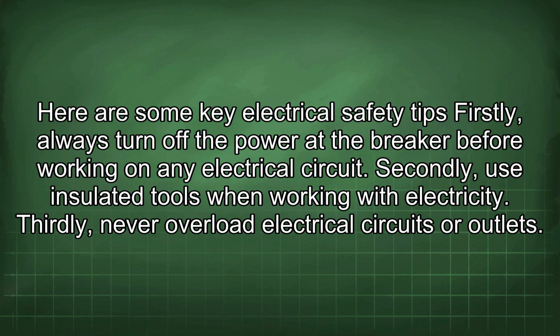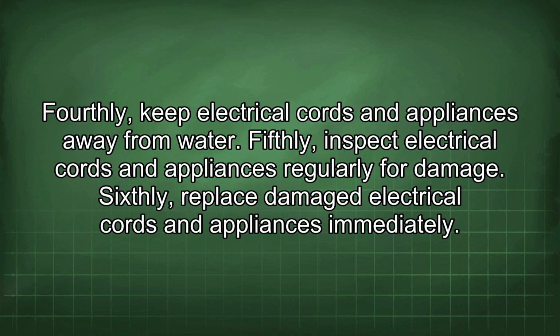Firstly, always turn off the power at the breaker before working on any electrical circuit. Secondly, use insulated tools when working with electricity. Thirdly, never overload electrical circuits or outlets. Fourthly, keep electrical cords and appliances away from water. Fifthly, inspect electrical cords and appliances regularly for damage. Sixthly, replace damaged electrical cords and appliances immediately.